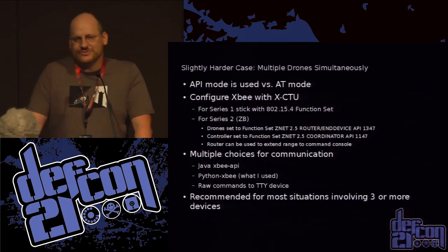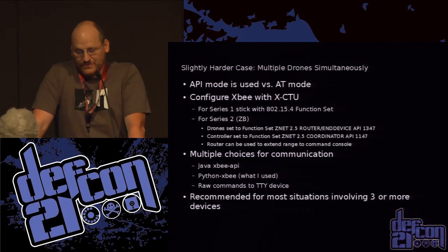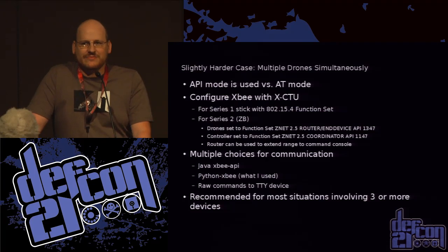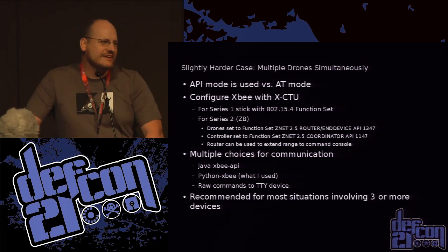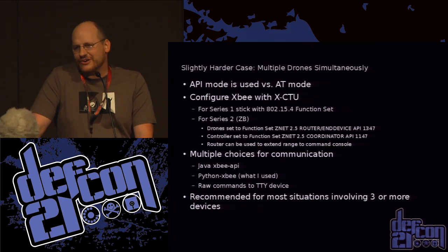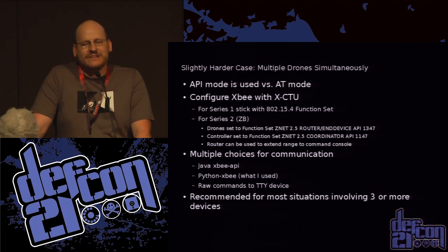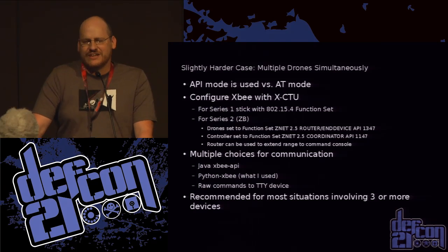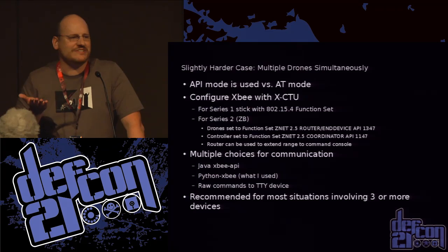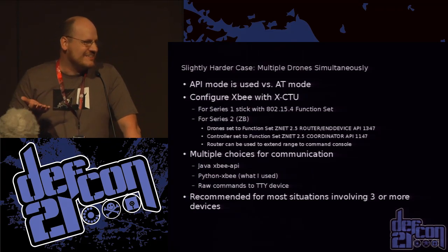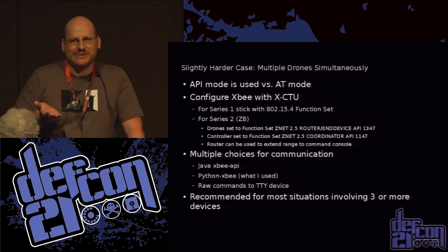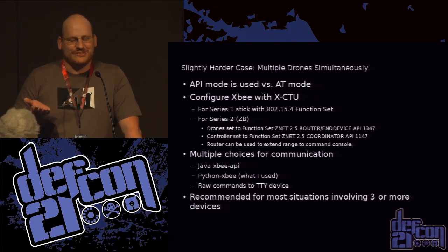I can also use an API mode, which is what I would personally recommend. The nice thing about API mode is that things are sent in packets, and it's a lot better performance and error correction and all that good stuff. By the way, a little tip: if you didn't configure all your modems to use API mode and you're standing there going, it says it's receiving, why isn't it doing anything? And you're thinking, it's my Python scripting. It's probably just that you misconfigured the modem.